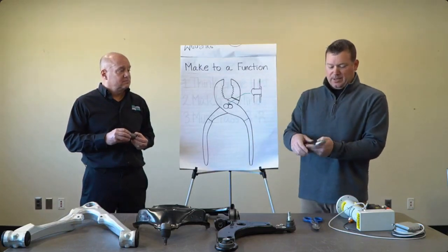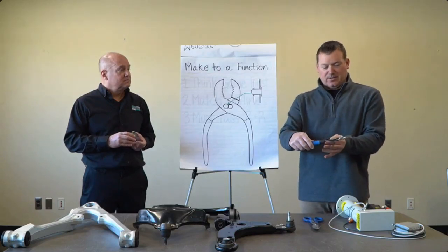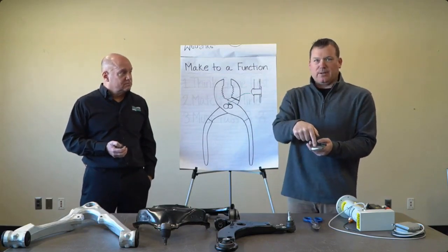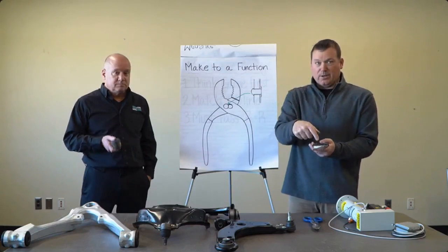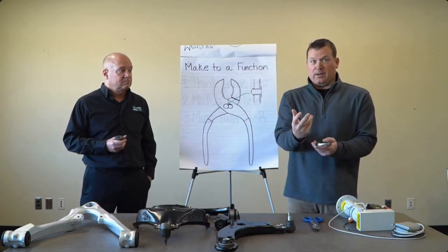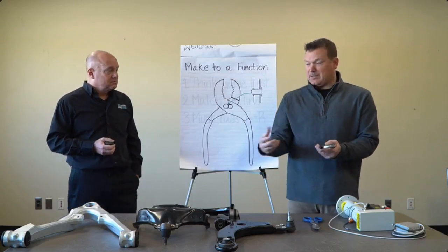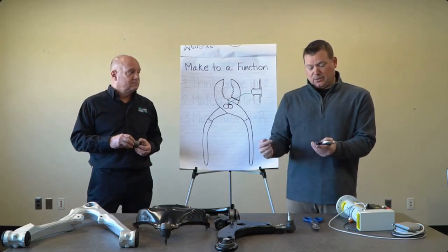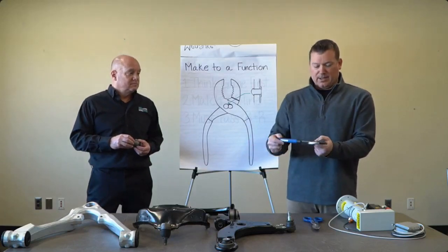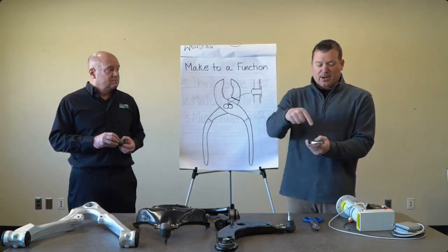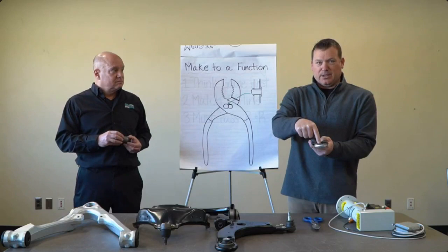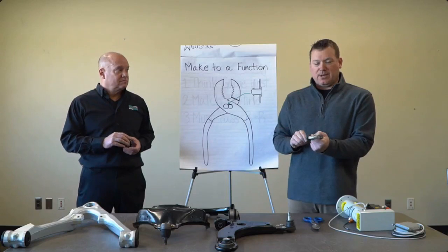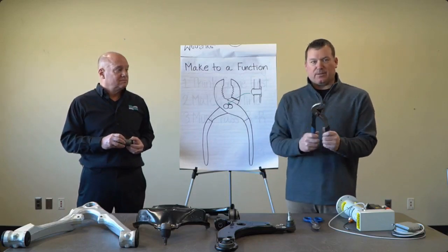Typically you have a rivet here that holds the two halves together. What we typically do is we'll have a press that'll upset the rivet or crush the rivet, either with just straight linear force, or sometimes we'll utilize some type of orbiting rivet head on the end of our press, but we basically get the force feedback from that. And then we'll have another actuator, either a torque system or a torque unit or another press that moves the handles in and out. And based off how far we crush that rivet or how much effort we put on that rivet, we can then control that and get the necessary torque that we need in order to have this function how it's supposed to.